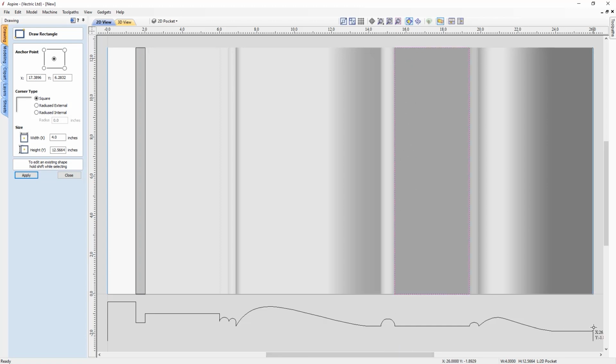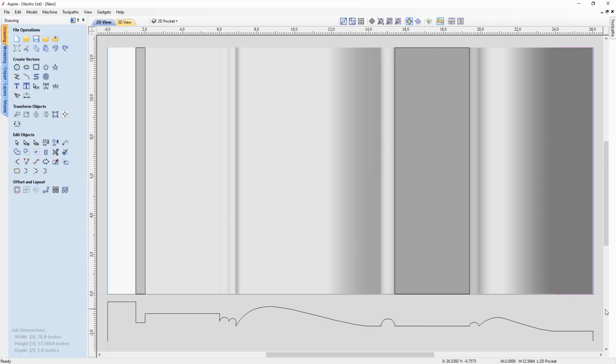And then finally we want to snap to create a shape that represents this flat area. So we'll just wake that point up there, like so, and then we can see we've got a snap there, so we're just going to drag that up to the top. We're snapping in place, and there are our vectors there, so we can close out. Here we have 3 rectangular vectors that represent the 2D areas of our part.